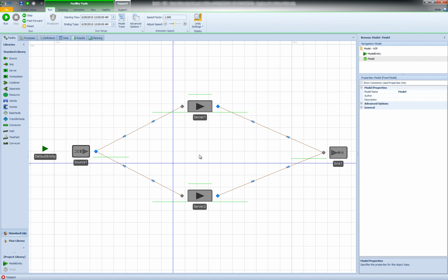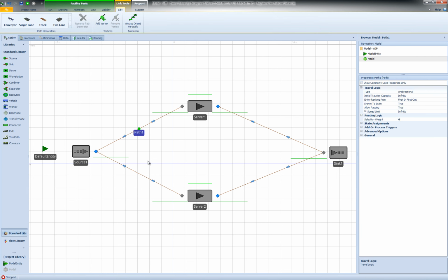So we're still talking about the situations where our entities do not have a destination. The last situation that we're going to talk about is when we want the entities to take a specific path. In this case, I would like all my entities to take path 1. Of course, now we know how to do this using selection weight. We can change this selection weight to 0 and have a non-zero selection weight for our path 1, and all of the entities will take path 1.